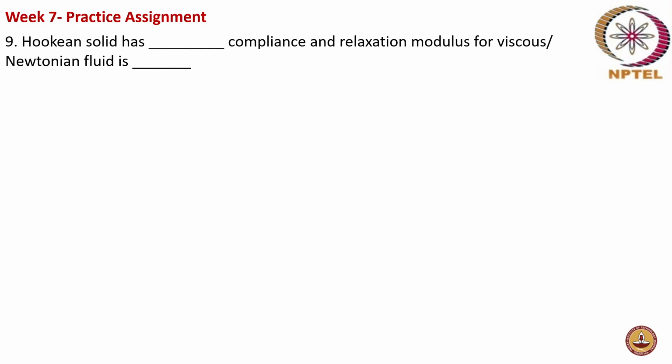What happens to compliance? Ma'am, is it complete compliance, like 100%? Can solids have 100% compliance? No. So where does compliance come into the picture? In which experiment does compliance come into the picture? When it is under creep, ma'am. Yes. So what is creep? Constant stress, variable strain. Yes.